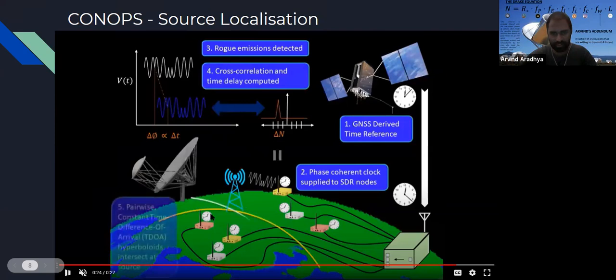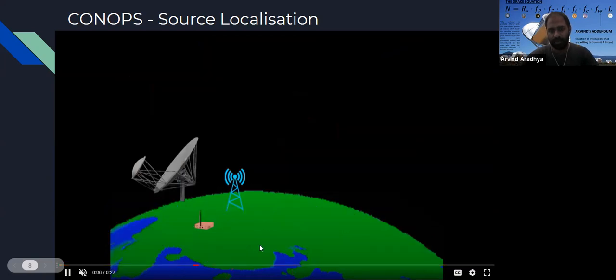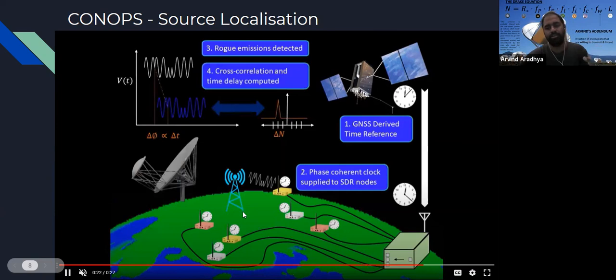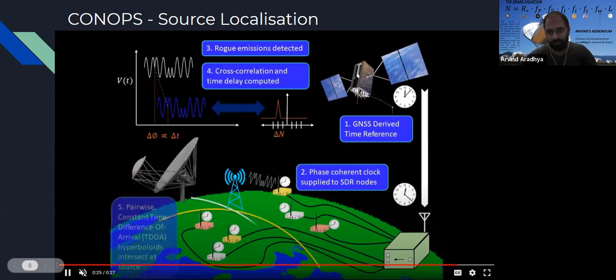So this yellow curve is the possible location in the tower as determined by just the two yellow radios. And then similarly, you have a white hyperboloid, which is for the possible location determined by the white radios. And then you have the same thing with the red. And then wherever they intersect, and they will intersect if it's a genuine signal, because the math works out that way, you end up being able to say where this particular source of interference came from.